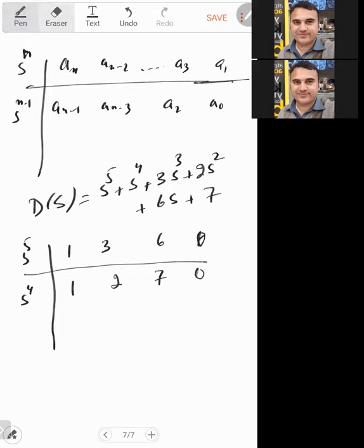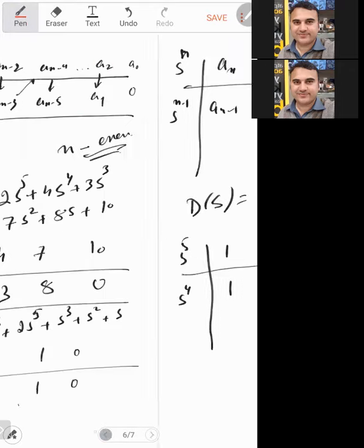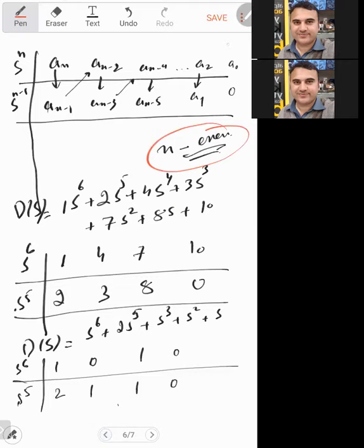So this is for when the power is odd, so we'll come up with this one, and if the power is even, then we'll come to the previous one, this one. Anyways, whatever the power is, you can easily transform the information using this procedure. We start with the highest one, and then the next one, and then just put the coefficients in this specific order. So we get the initial table of the Routh table. So the initial table is formed.